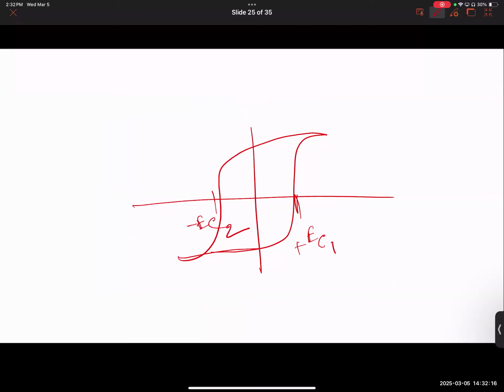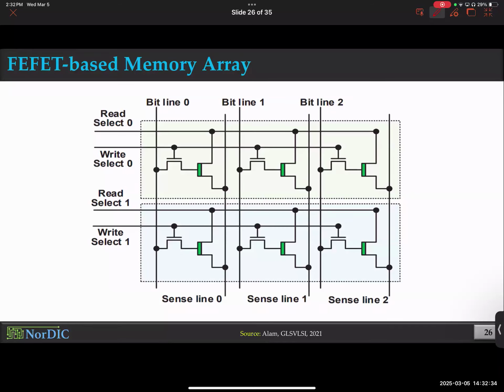And there are other reasons why, because of the interaction between dielectric and ferroelectric, some depolarization effect occurs, and that leads to asymmetry. But these are getting into real weeds in the FFET. It's a good question, but it's not really that much of a concern, honestly. By using intelligent fabrication methods, we could minimize those effects, we could minimize those asymmetries.